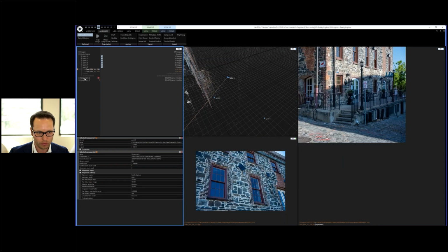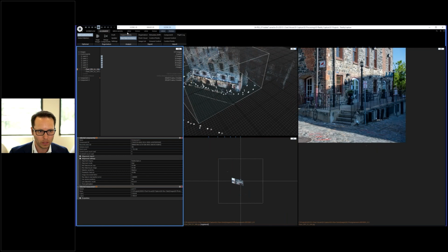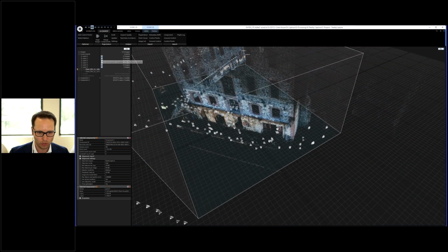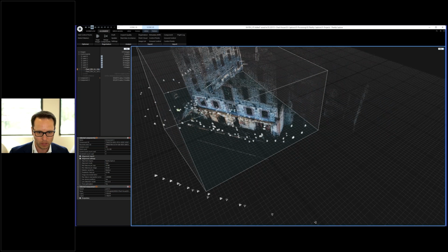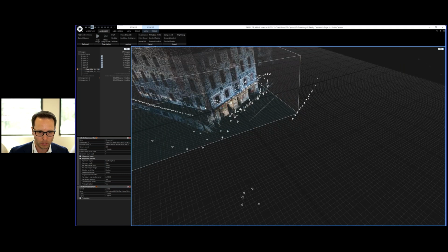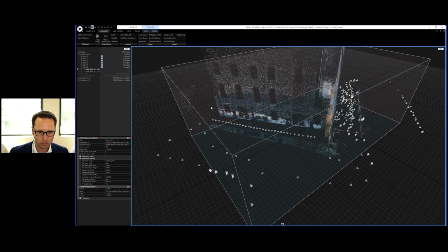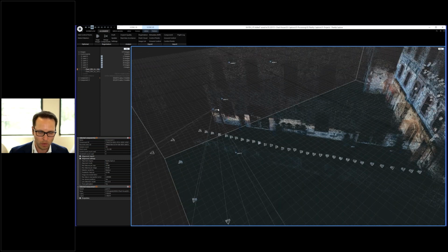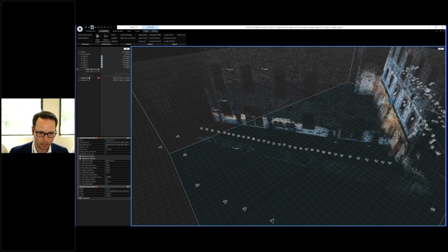So if we open component 1 and we switch to 1+1, deactivate add control points, and just pan around, we can see that in component 1, we still have only 5 control points. We have from 0 to 4, we don't have point number 5. So what we need to do is to make sure that we add that in here.